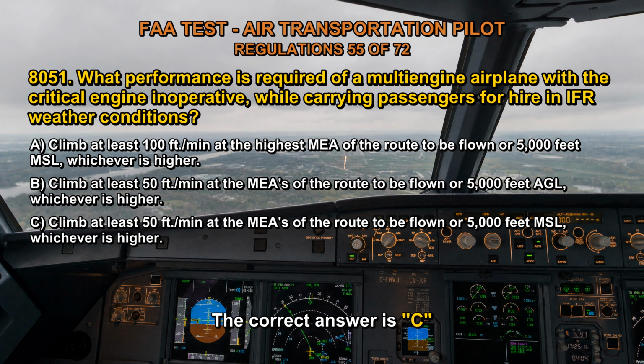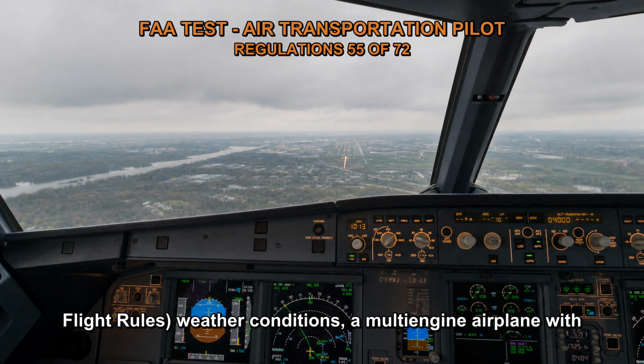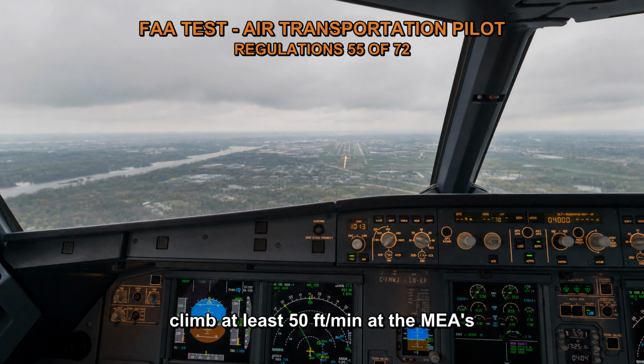The correct answer is C. When carrying passengers for hire in IFR, instrument flight rules, weather conditions, a multi-engine airplane with the critical engine inoperative must be able to climb at least 50 feet per minute at the MEAs of the route to be flown or 5,000 feet MSL, whichever is higher.